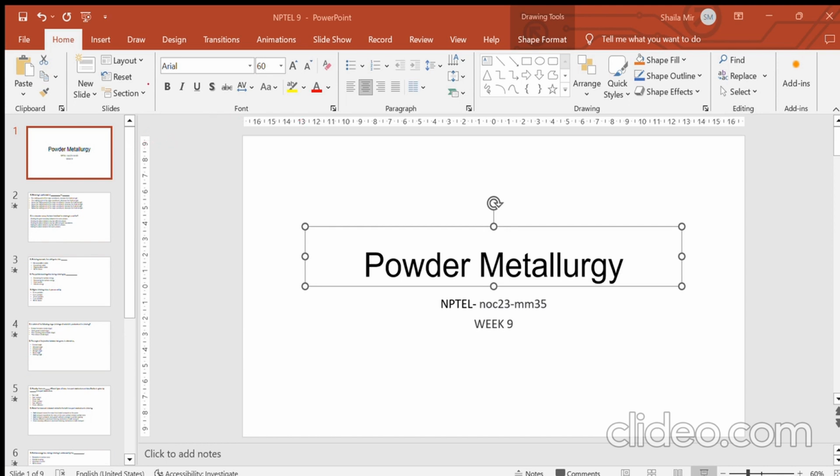So which of the following will have a predominant shrinkage, right? Obviously in contact formation there will be no shrinkage, because this is just the formation of your interactions. Then there is neck growth, but still there is no shrinkage happening, because the area that was present in stage 1 is still the same, only the particles have coalesced with one another, so the area remains the same.